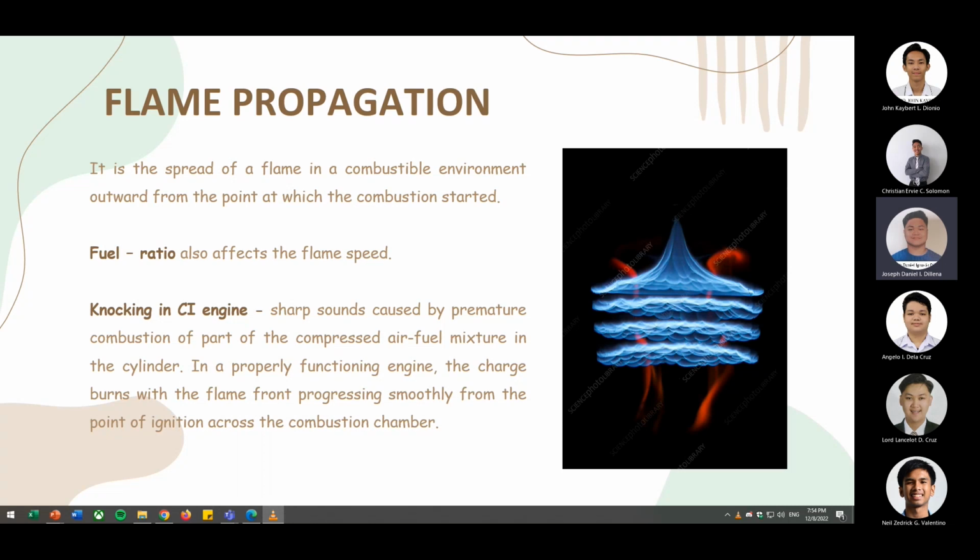Flame propagation is highly reliant on the conditions affecting flame travel, on the quantity of charge present in the chamber, and on the turbulence, because the peak pressure is dependent on flame speed, which is reliant on the spread of flame. If flame propagation is too brief, combustion is poor. The interplay of the charge and the turbulence is what mixes the burned mixture and unburned mixture, boosting the velocity of reaction as a result of contact.